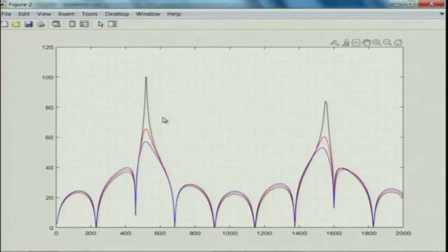A highly porous section is nearly equivalent, and the results would converge as the porosity tends to 100%, because it is like an open ended section, there is virtually nothing there. It is only because of machine problems and round off errors that you are not able to calculate beyond a certain value, but the curves would approach that of an open ended duct.